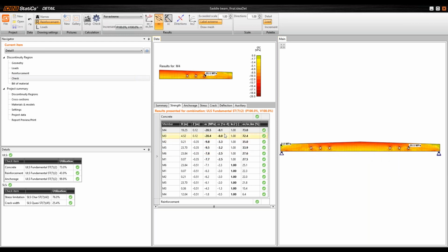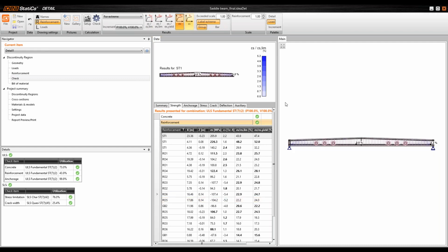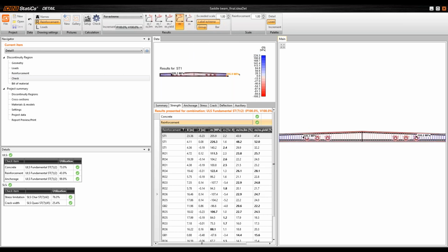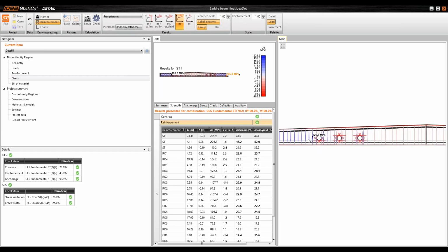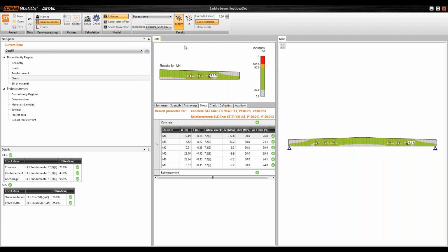So the maximum value is compared to the design value, and as I mentioned, the maximal stress is on the rebars, but not on the longitudinal rebars. You can see around the opening where is the concentration of the stress on the stirrups mainly.